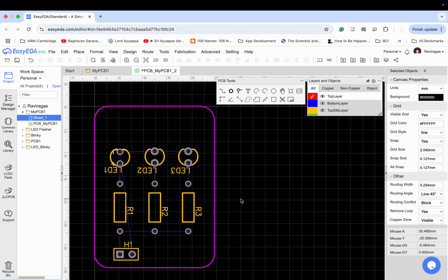So now let's go ahead to do the wiring. To wire up the tracks, click on this track here and click on any pad and you can wire. Before we do that, our design in this case is going to be a two-sided board, but all the components are on one side, all the tracks are on the other side.